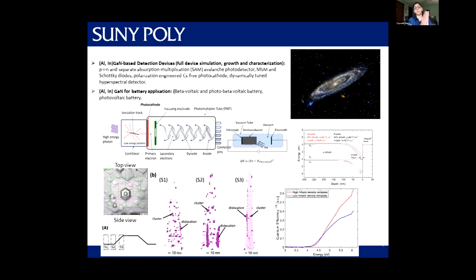And a photocathode is really a piece of what goes into a system of detection. So you can kind of just see how the photon comes in, and then you have the whole scintillator, and then you have the photocathode and the rest of the multiplication of that detected photon. So we are working on that photocathode that goes right there. If you look at the band diagram in the middle of the page, you see that photocathodes currently are made by putting a thin layer, almost less than a monolayer, of cesium at the surface of these compound semiconductors.